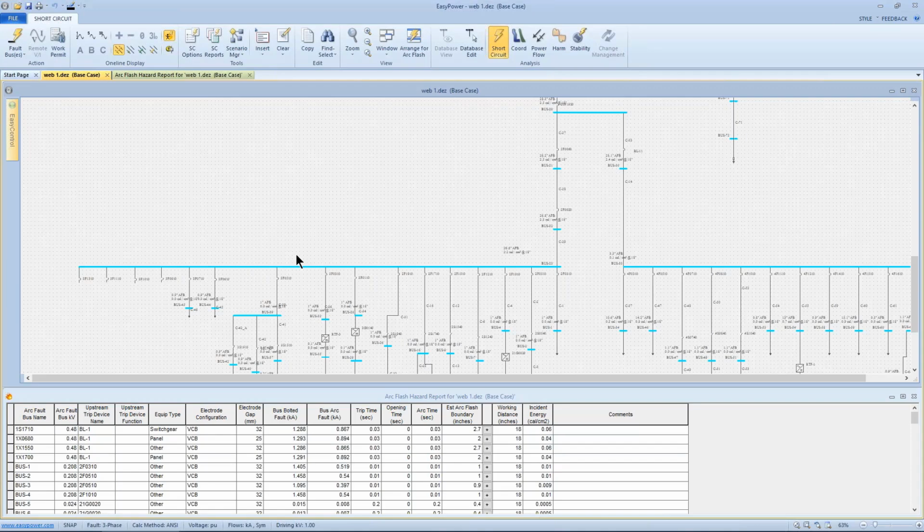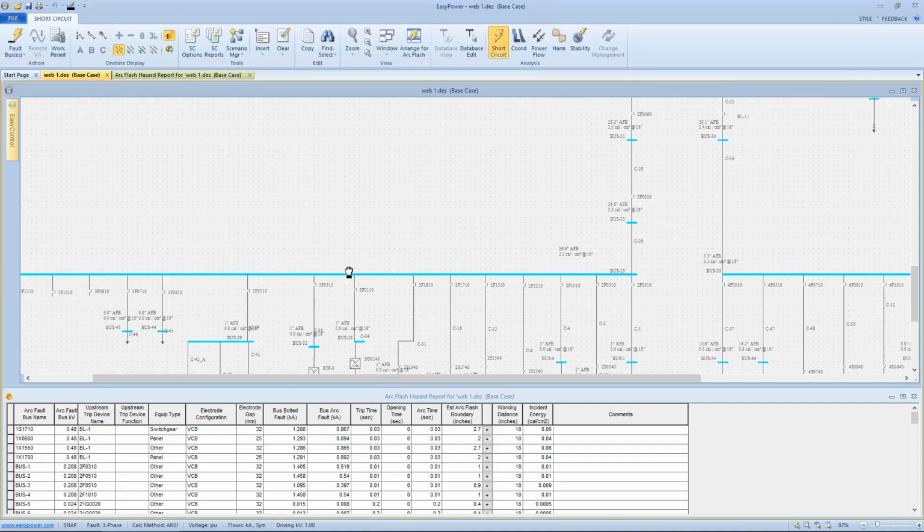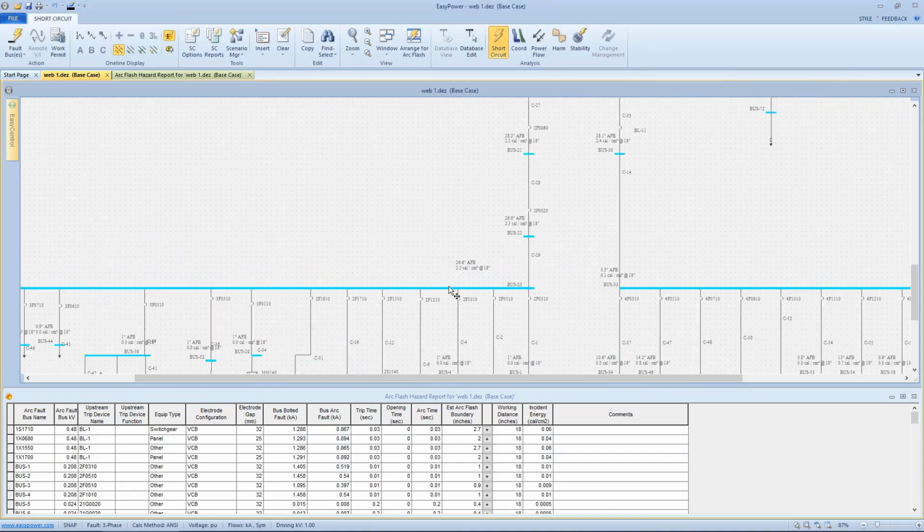So bottom line here is the recommendation of 1584. It's not to ignore or assume that these are not an issue, but to basically limit the arcing time, because in fact we are going to have exceedingly low arcing current. Okay, so that's 1584. Now let me go back to my soapbox.